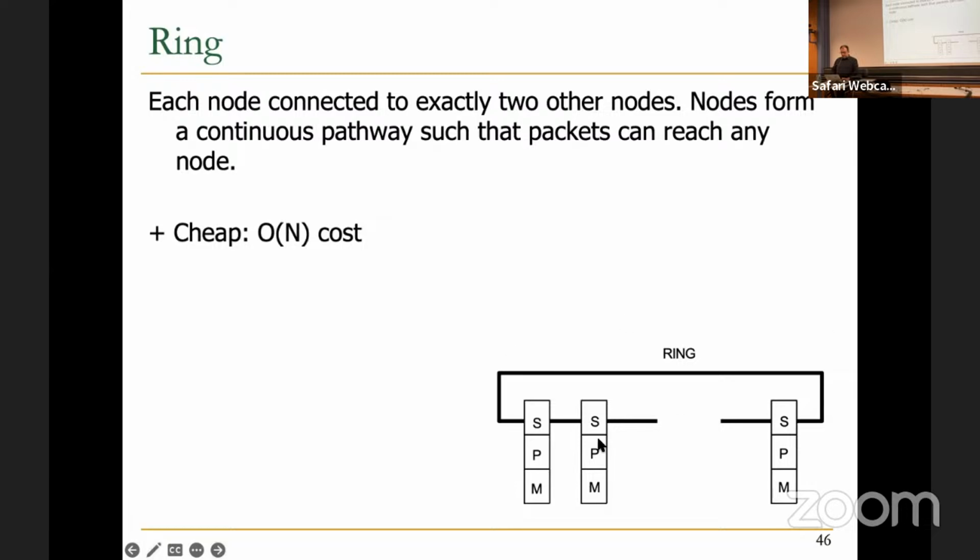With a ring topology, you can have this wraparound, and that provides some path diversity. Assuming your ring is bidirectional, because a ring can also be unidirectional, such that you cannot go two ways. But as long as your ring is bidirectional, between every pair of source and destination there should be two paths, right? So you have some path diversity, which is good for performance and also for reliability, because if one of these paths is faulty, then your ring becomes an array essentially, but your network is still connected. Of course, it cannot tolerate more than two faulty nodes.